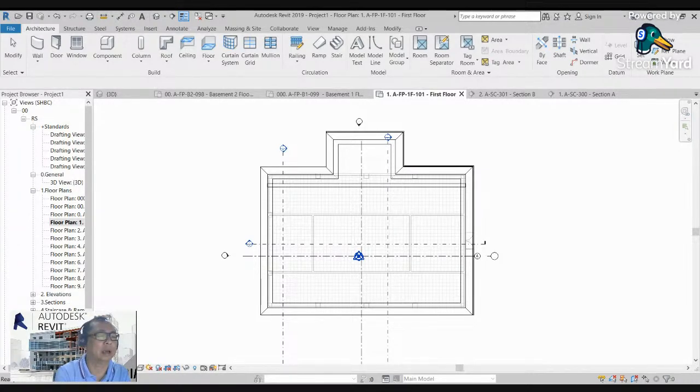We will run this on Navisworks, and then the Navisworks will detect the clashes on different models per discipline. And then the Navisworks will give the code number and then that code number you will enter on your model. For example, you are fixing the clashes on your Revit model, you will enter the ID code, and then it will automatically show you where is the exact location of the clashes between the MEP, structural, electrical.